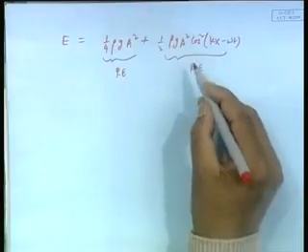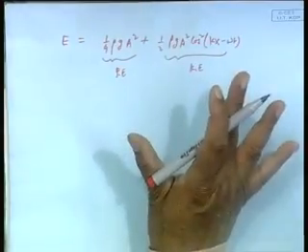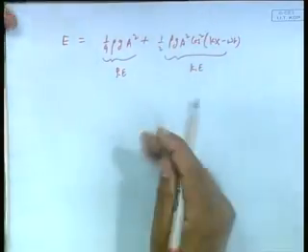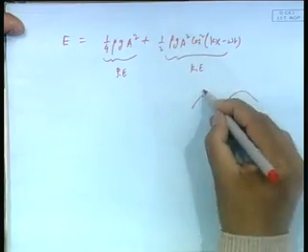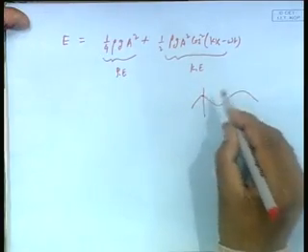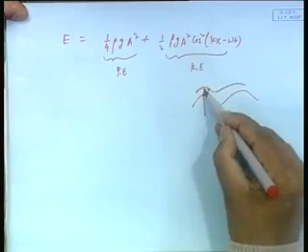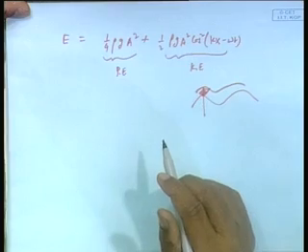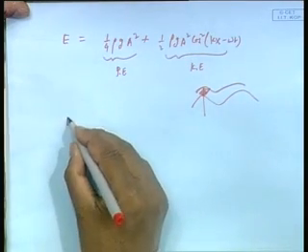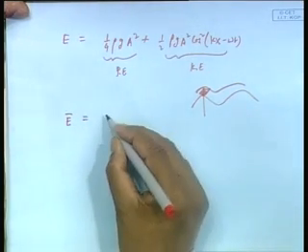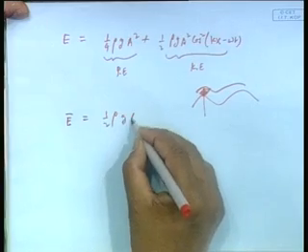Now, if I integrate the energy over one period, measure the energy from 0 to time t, total energy in that, and divide by t, then what I get is the average energy over a surface area of 1 unit. If you do that, you end up getting E bar equal to half rho g a square.